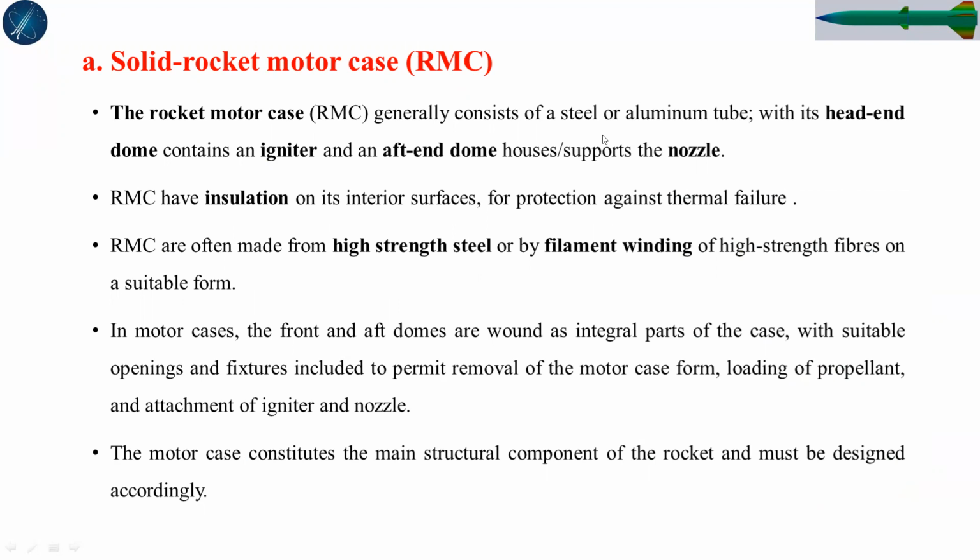It can be steel, aluminum, or other material based on the amount of external pressure or aerodynamic loading that can affect the shape. If we expect much external aerodynamic force, then we use stronger material. But in most cases, aluminum tube is used because of the lightweight of the material. In rocket design, light weight is one of the important parameters.